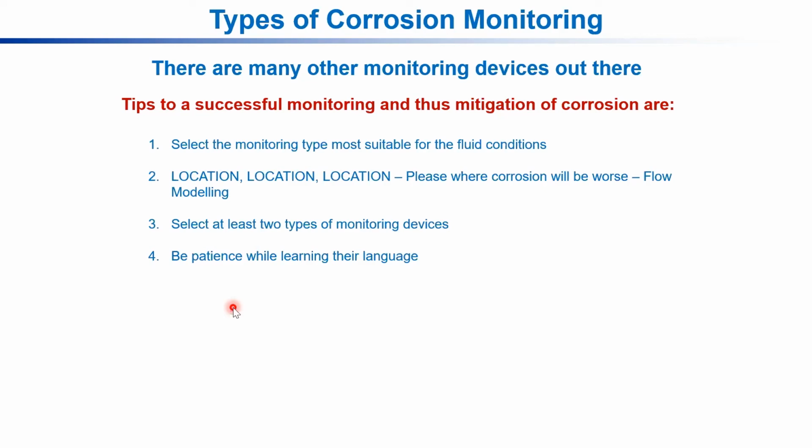For example, pH, alkalinity, bacteria, depending on the type of bacteria, you are going to have to do it on site. So CO2, dissolved CO2, dissolved H2S, many of these need to be done on site. Make sure that you follow the proper procedures to do the fluid analysis, because you may be losing a lot of important information if that is not done correctly.